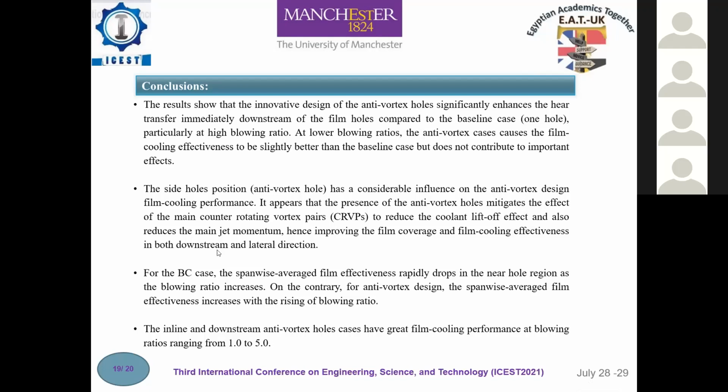Finally, the in-line and downstream anti-vortex holes cases have a great film cooling performance at blowing ratios ranging from 1 to 5, and this is the important conclusion in this study.